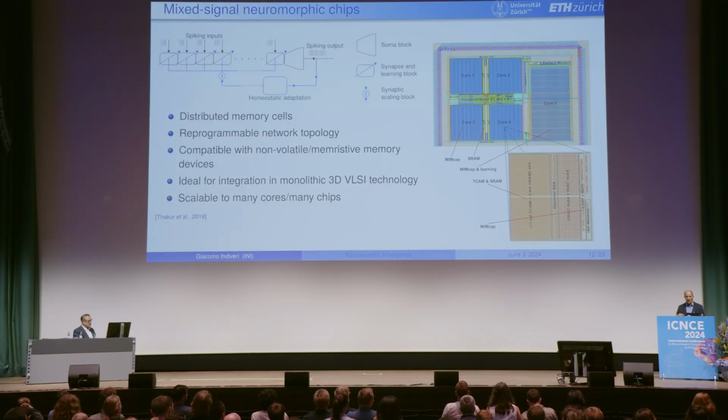So if there is a match, whenever one neuron on one core or another chip spikes, it will broadcast its spike to all the synapses. The ones that have the right tag will then receive that spike and establish the connection between the presynaptic and the postsynaptic neuron. TCAM cells take up more than 12 transistors, SRAM more than 6 to 8, depending on the implementation.